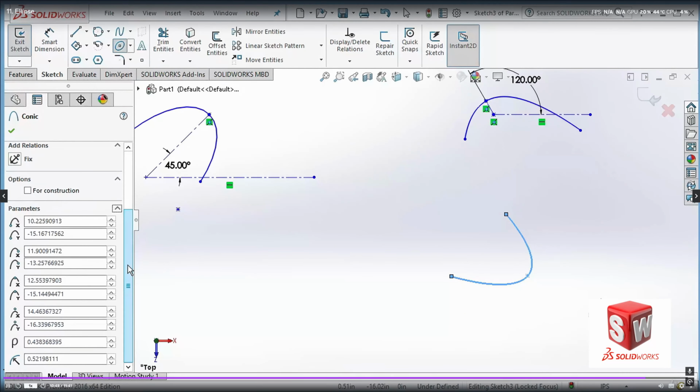You can see, go by clicking on parameters. I have a start point, I have an end point, I have the shoulder, and I have the vertex. So we have different options for conic. And of course I have the RHO parameter, and finally the radius of the curvature.